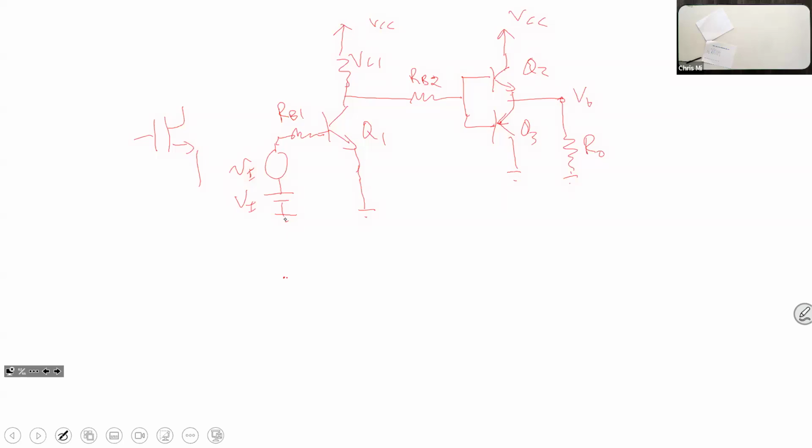Because we need to at least have enough voltage to overcome... The thing that makes it slightly more complicated is that we have the resistor between the source and Q1. Right, but the base current, think about it, is very small. And when we do the initial analysis, we can assume it's even 0. So if we're assuming it's 0, we need 0.7, because everywhere there is an arrow on the leg, we're assuming there's a diode. So you need 0.7 to bias the base to emitter so that it can be forward biased, it can be on.